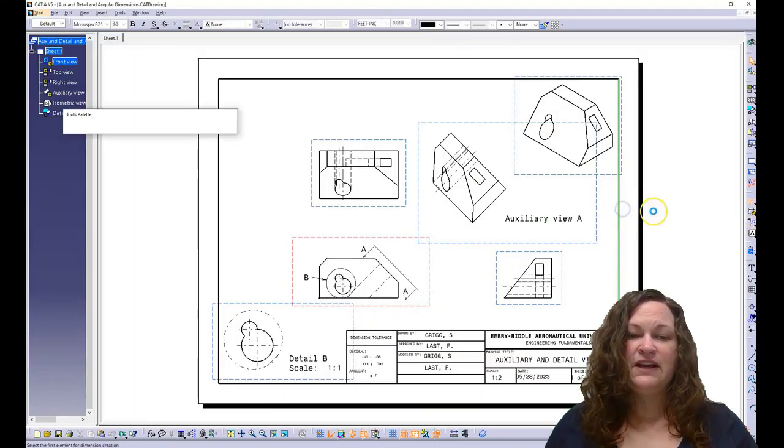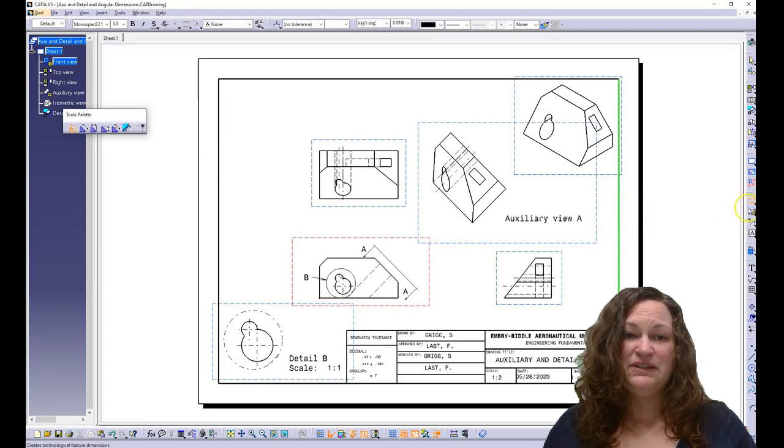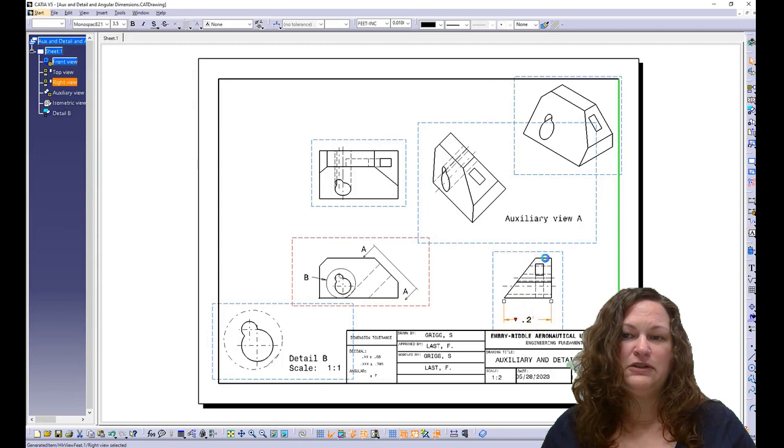I want to go through an exercise of dimensioning with angular features. So here we're going to start out by finding all of our normal surfaces and dimensioning those length values first. And that helps us set the stage for some of our angular measurements.